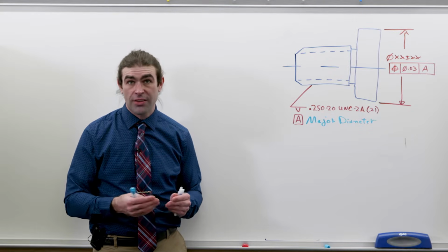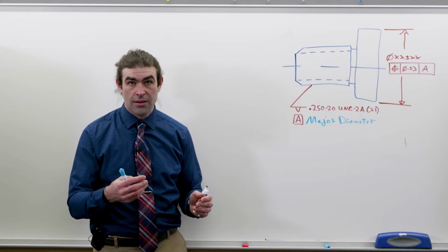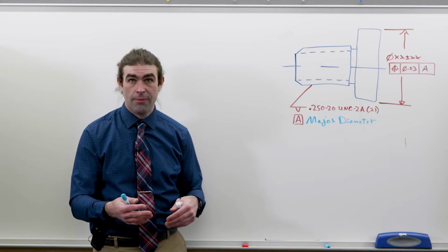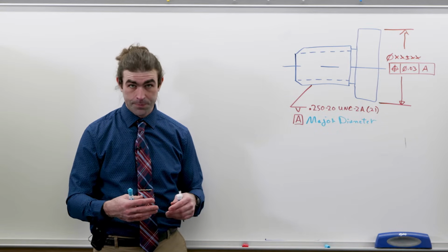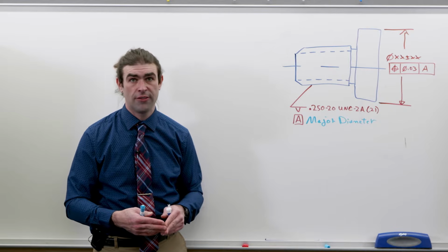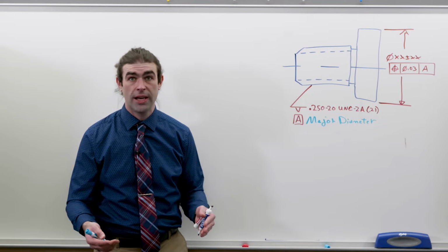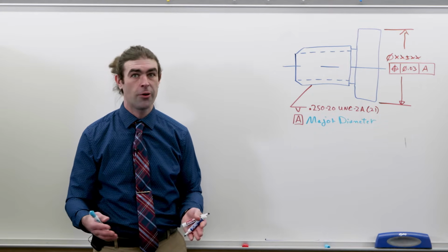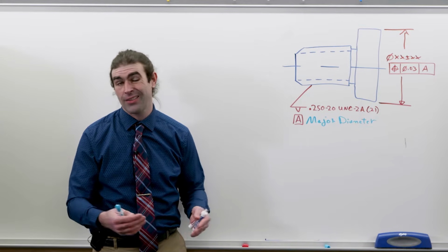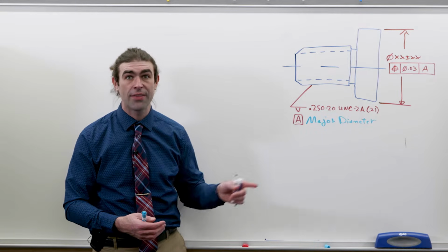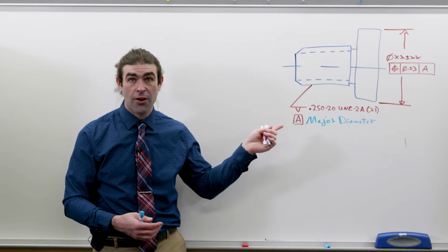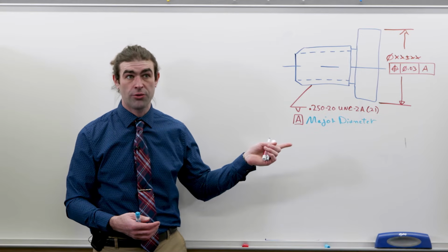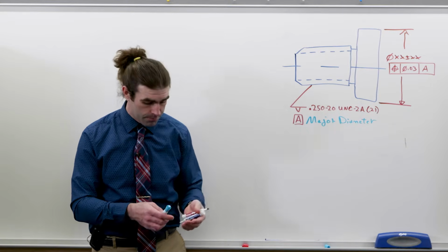The downside, design-wise, is that the major diameter doesn't locate the thread as well as a pitch cylinder, so you wouldn't want to do this if it's really critical to locate something. I mean, you really shouldn't use threads to locate things, but I guess it just depends on the stack up you're looking at. This could induce error at assembly that's difficult to keep track of. Right?